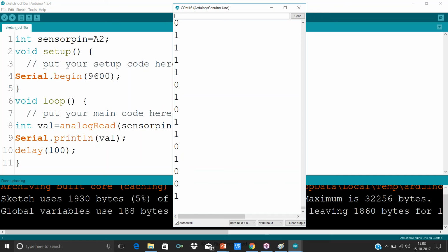Mr. Prasant, I hope your sensor might be working in the opposite way. Probably when there is no object, it might be giving you values like 1019, 1029, 1039. And whenever you put an object, it will give you low values like 33, 34, 35, or up to 40. Is it responding in that manner?